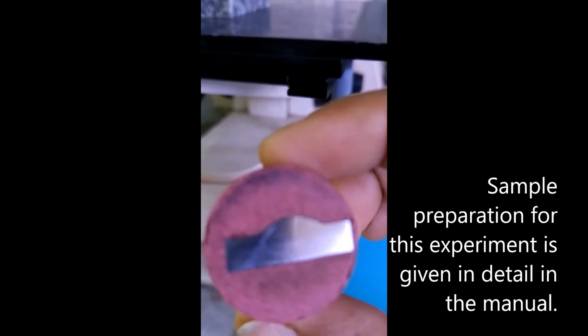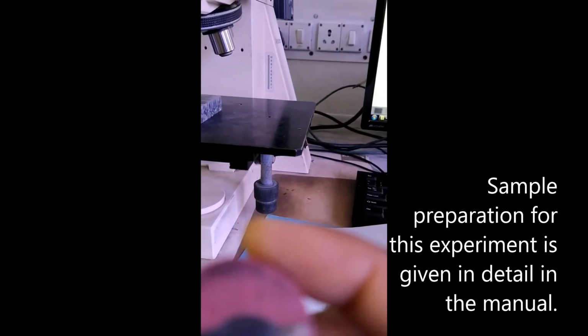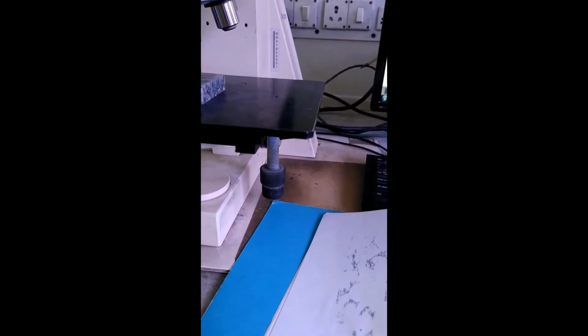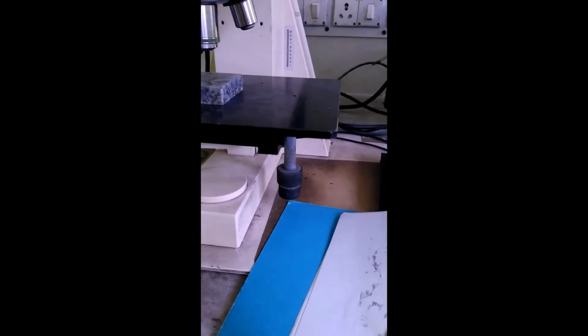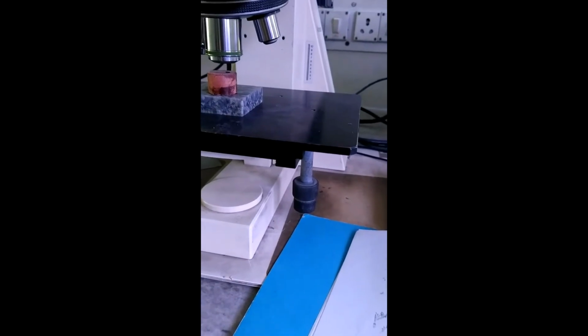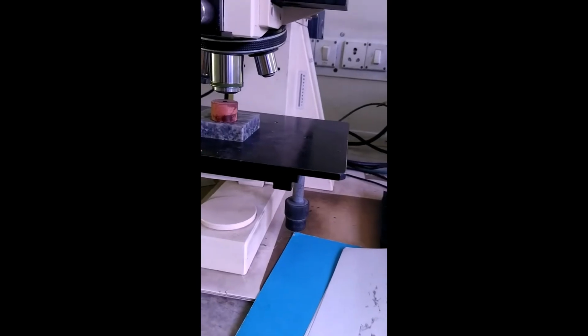So the heat affected zone is divided into 4 zones. One is transition zone, one is refined zone, one is core zone, and another is fusion zone. And from the unaffected zone to the fusion zone, how the grain is affected by the heat and how its grain structure becomes different, we can study in this experiment. So first we see